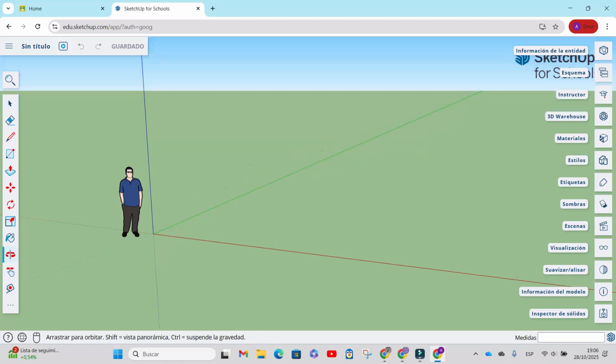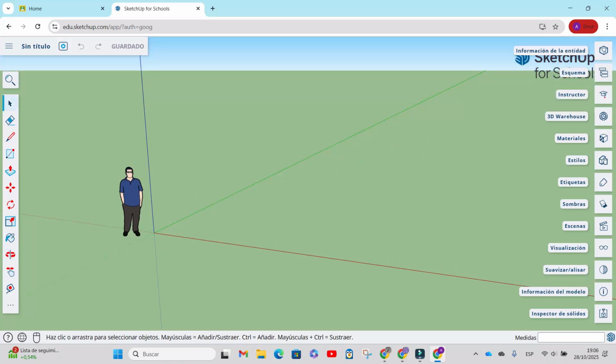With this position, we are going to draw according to the instructions on page 60. We are going to draw a rectangle and then pull it up. To draw a rectangle, we choose this tool. You see that we can click in the origin and moving there is a rectangle which follows the pointer.